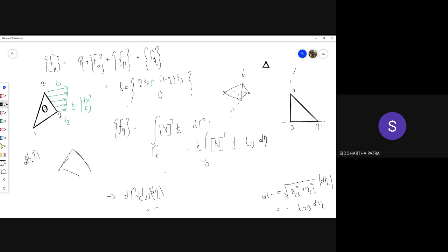Okay. Now typically, if a software uses the positive value of the Jacobian, okay, to be the convention, that is counterclockwise numbering as the convention, then it will throw an error when it gets a negative value of the Jacobian. Okay, and that can happen in two ways. One is while doing the solution, you are getting calculations which indicate that this element has been flipped.